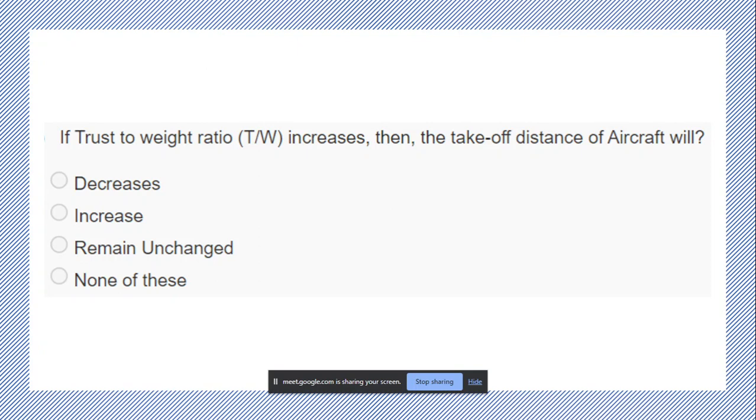Okay, so let's try to do this. So what was the liftoff or takeoff distance? You can take either of those. So takeoff distance is the whole distance, the ground roll plus the liftoff. So S liftoff, we know the equation. So that was 1.44 W square by rho g S CL max and thrust, right? This was the equation. How did we come to this?